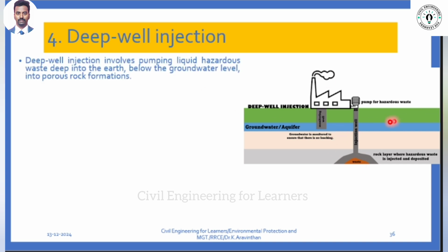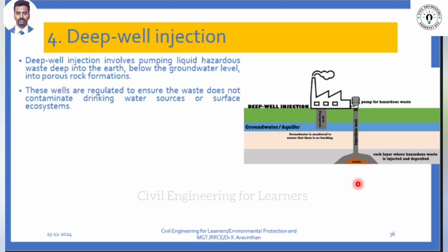Can you see the groundwater level here? Below the ground they have groundwater. So it should be drilled deep into the earth, then they should dispose. Can you do solid waste disposal in deep well injection? Solid waste cannot be pumped. What kind of waste can you do this with? Liquid waste. Can you do gaseous waste? Soon after you pump it will come out. So only liquid waste can be injected like this.